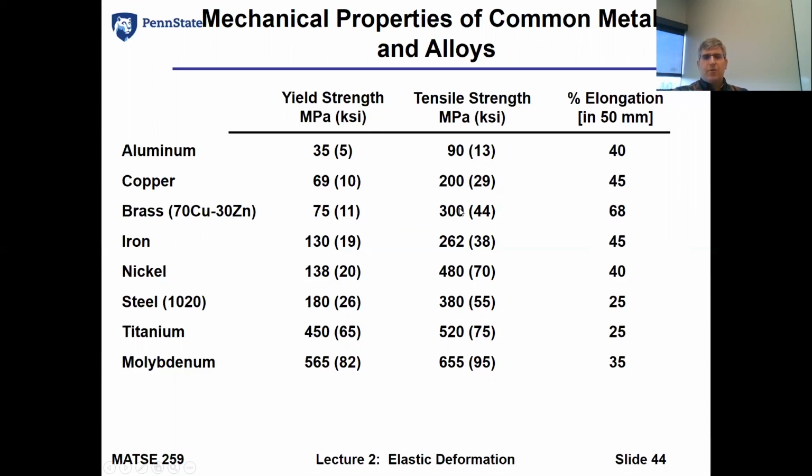And so we start to see why we use alloys for different applications, just taking something from a copper, and in this case with a brass, adding about 30% zinc. We get a kick in elongation, we get an increase in tensile strength, and we get something that's a little bit stronger in the yield strength. But this allows us with brass to be able to change its shape. Imagine hot water piping and being able to do tube bending and pipe bending with that.